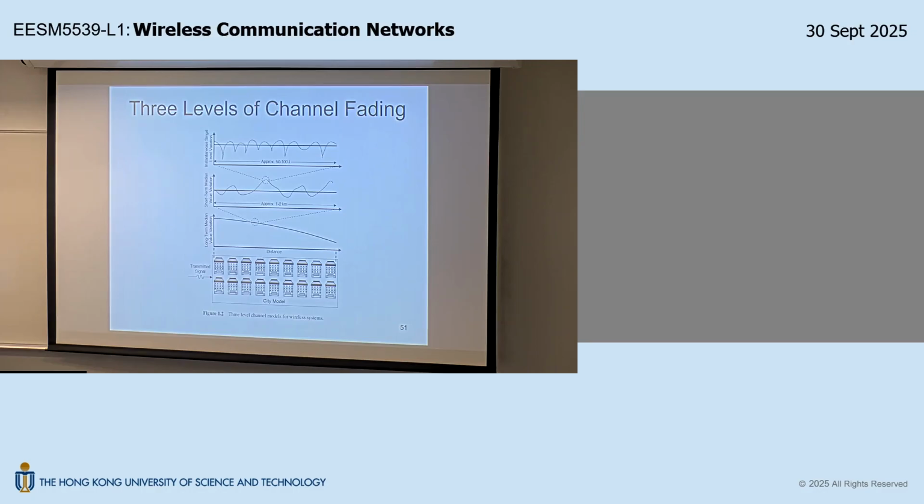So this is a transmitter, and the transmitter signal is coming from this direction. Imagine the base station is on this side, and the mobile is moving along this city center. As you move in this direction, due to path loss, your distance separation increases. Therefore, your receive power gradually decreases. This is due to the path loss effect. Now, if you take a small piece and zoom in, you start to see fluctuations. This fluctuation due to shadowing in this particular terrain is like this.